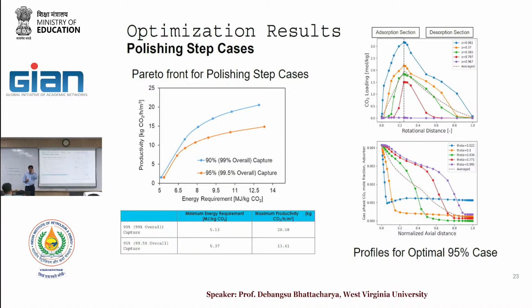So, as I said, just like other cases, you can solve a dynamic problem. The dynamic problem will converge. It might take you like 2 or 3 hours to converge the dynamic problem. When you see that everything has settled down, take a snapshot, use that snapshot for steady state, and then you can solve for steady state. Okay, any question here?